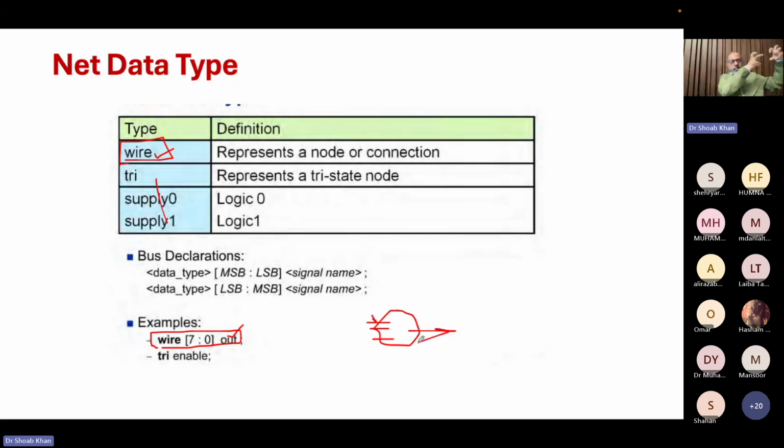So some input driven, you calculate, and you drive some value. A wire type of variable must appear only once on your left hand side, because you cannot assign a wire at two different times.